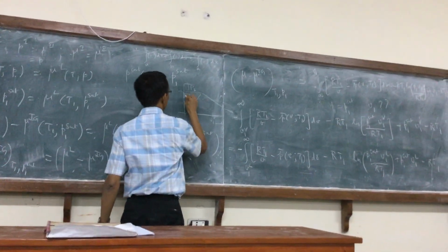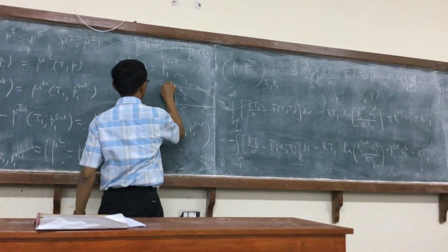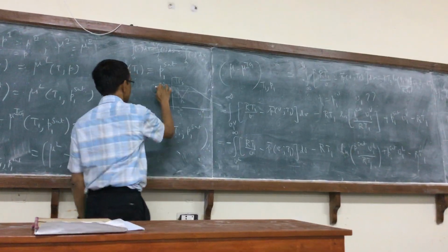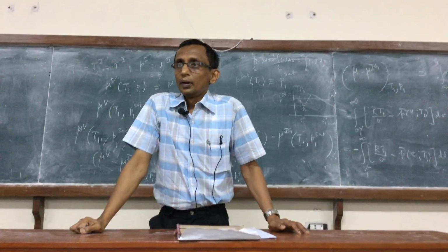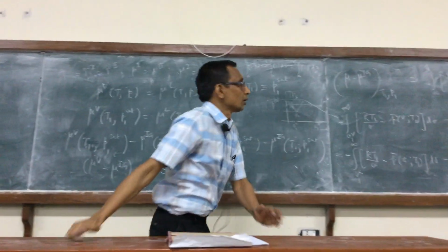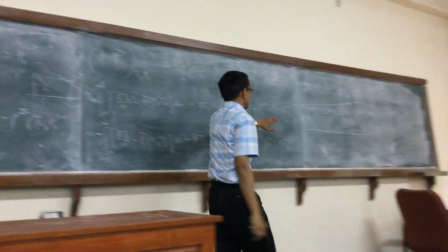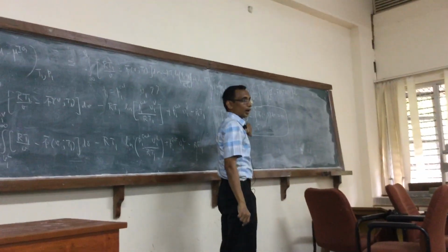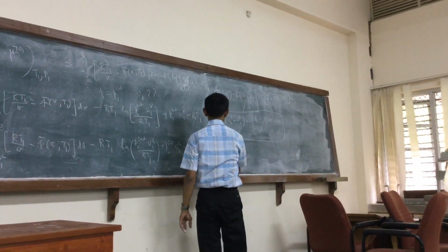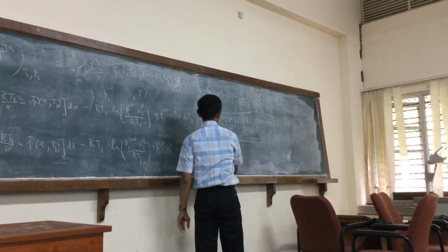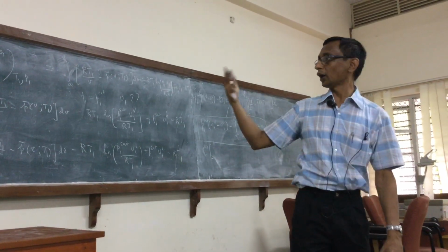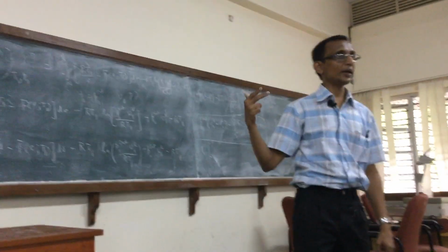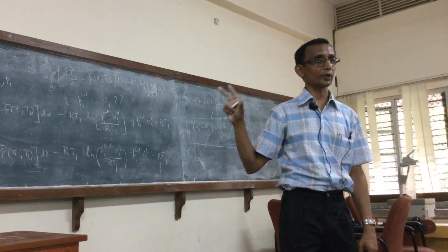So once I choose, let us say, some pressure P1 or P0, let's say, initial pressure. I don't know whether this is P1 sat or not, so I will have P0, and then I have to go and solve for V1B and V1L corresponding to that pressure.